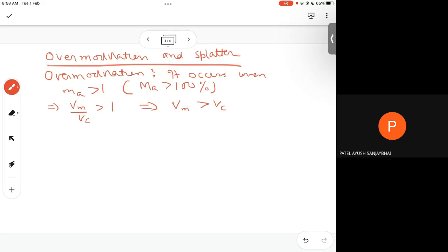But carrier is in my hand. I can choose the amplitude and frequency I want. But it should be a higher frequency because I want lower wavelength and lower antenna size and so on. I can keep my carrier amplitude smaller, but if my message signal amplitude becomes greater than this one, then we'll get overmodulation.